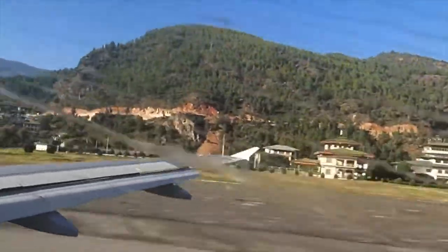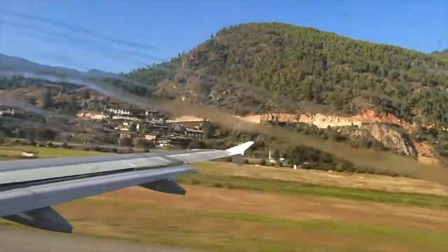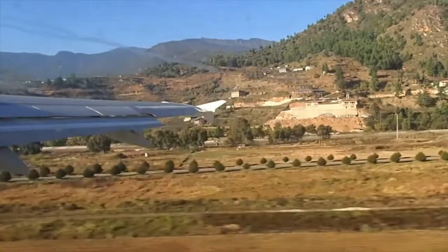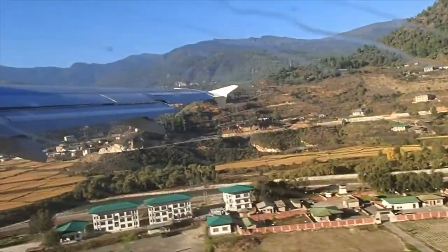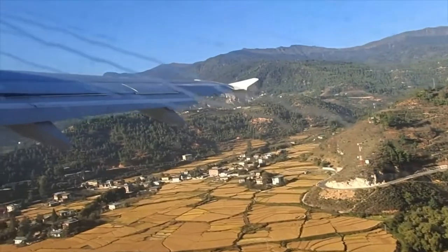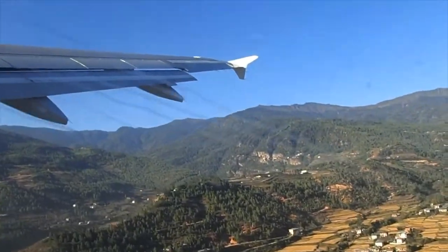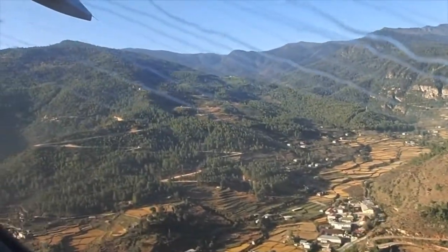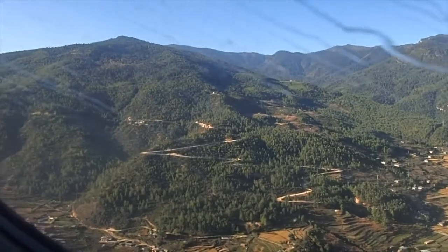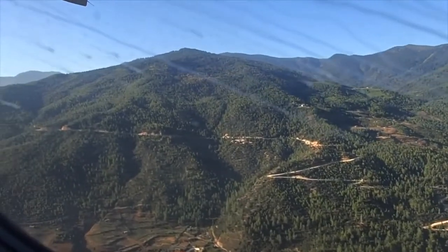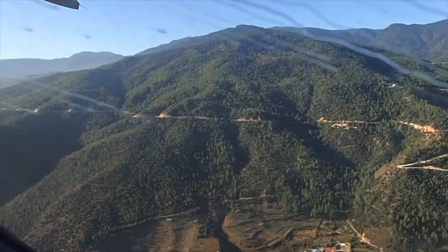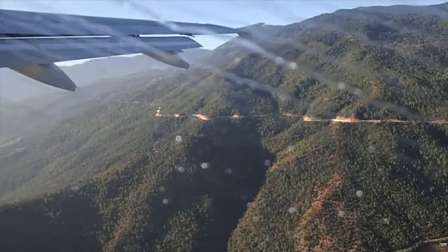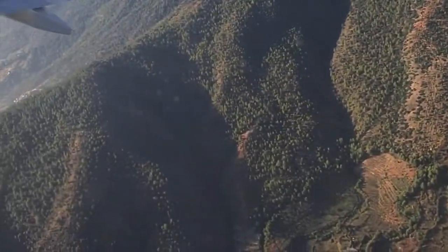Flying is an adventure for most pilots, sometimes more adventure than they really want. A pilot's report to Canada's aviation safety reporting program about an attempt to land through low clouds on a remote, icy runway is an example. The airplane's altimeter indicated that the airplane was still 300 feet above the ground, but the nose wheel struck the ice, the report says. The pilot immediately applied full power, climbed away from the ground, and returned safely to the departure airport. What happened here? The air pressure was lower at the destination airport than at the departure airport, but the pilot had not reset the altimeter because the airport didn't have radio weather data.